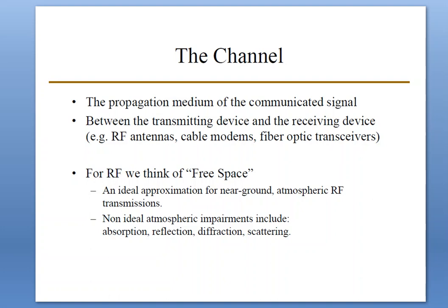Also, we assume that the Earth is infinitely far away, or that the reflection coefficient is negligible. The RF energy arriving at the receiver is assumed to be a function only of the distance from the transmitter, following the inverse square law used in optics. A free space channel characterizes an ideal RF propagation path.